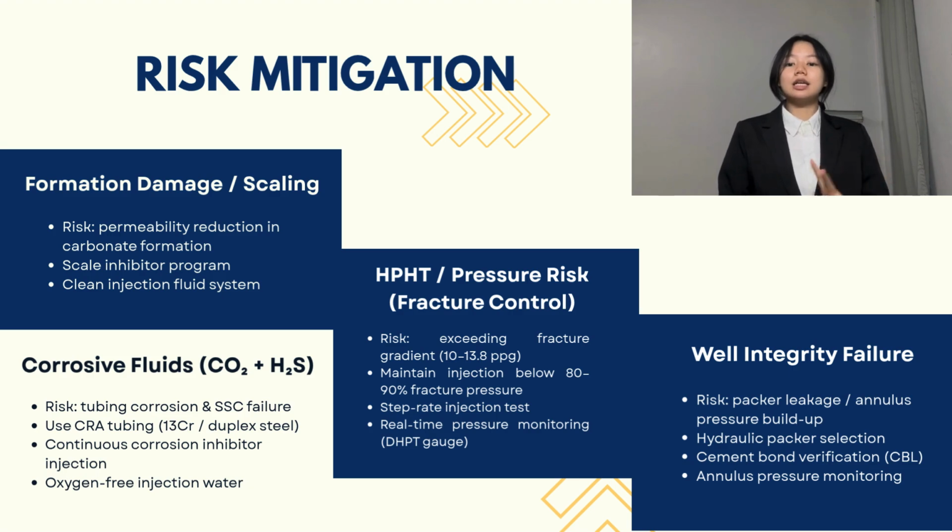Then the second risk is pressure and fracture control. During injection, the bottom hole injection pressure must be kept under the fracture pressure of the formation. If the pressure is too high, unwanted fractures may form, and then the water may move into an unintended zone. So to avoid this, we conduct a step-rate injection test and monitor pressures in real time, so the maintained injection pressure will be below the fracture limit.